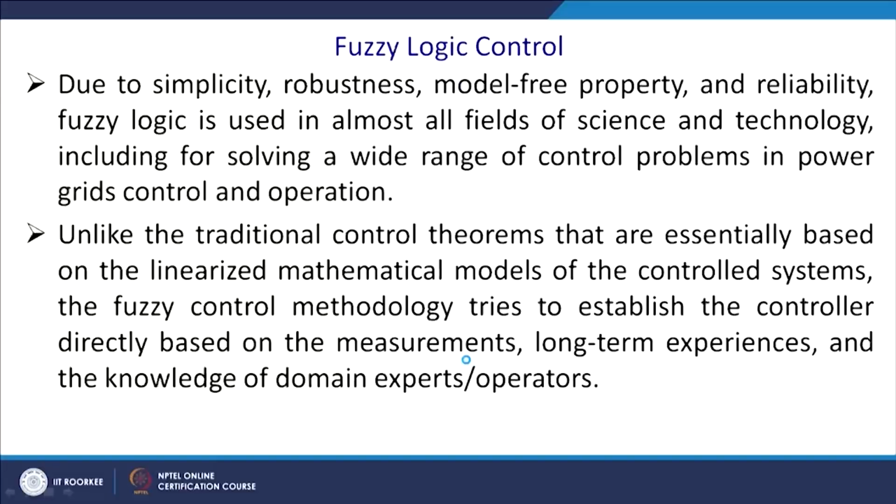Now, let us first discuss the fuzzy logic controller. We abbreviate it as FLC sometimes. Due to its simplicity, why simple? Because it works on linguistic terms, and that is what human beings are familiar with. Then the robustness, and you give a number to your membership functions. Say in your city, if it is 40 degrees centigrade you say it is the hottest, if it is 30 you say warm. So, accordingly in case of hot, what should be the membership function, you can linearly define sometimes, and for this reason it is simple.